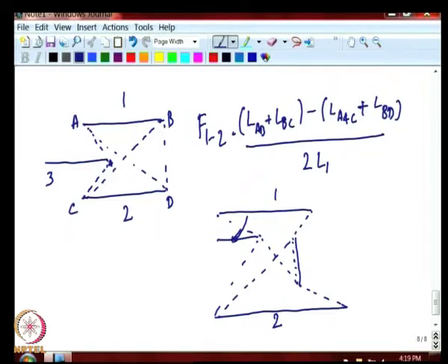And so, you can do some construct and see that, for example, here this ray from 1 can lead through this, but that is not a ray which will reach 2. So, that you have to guarantee that does not reach 2. So, then you can calculate the length of these 2 strings and get the answer. So, you can see that as the problem gets more and more complicated with obstructions coming in, you got to be a little careful about how you construct your strings and do a few trial checks to ensure that your triangles are drawn properly.